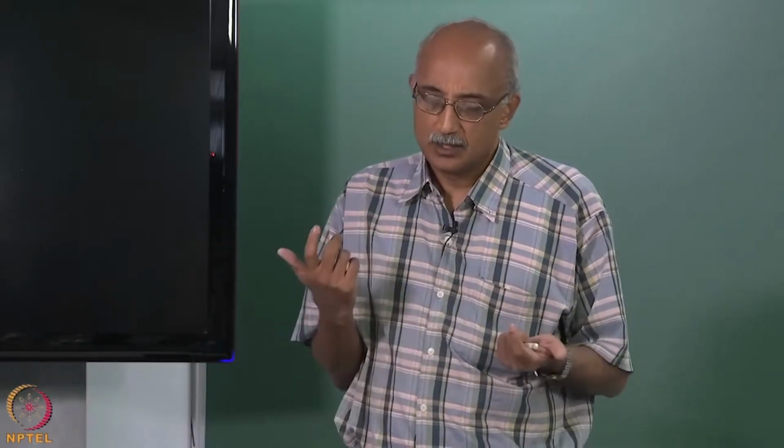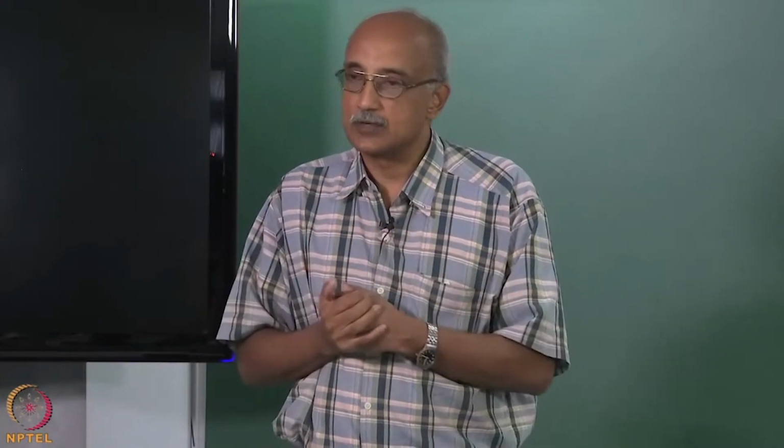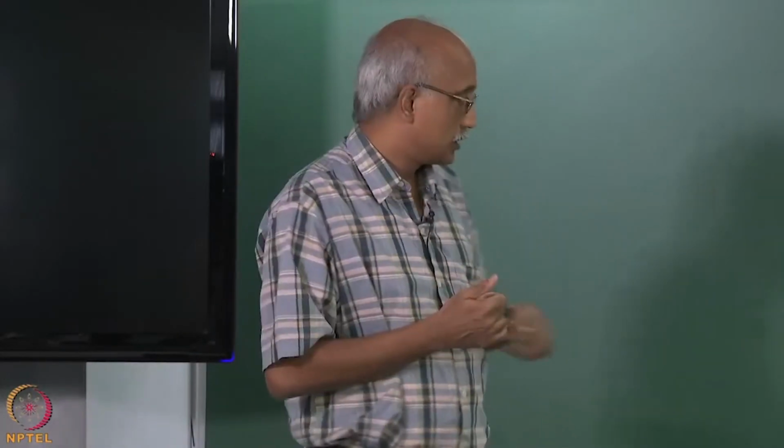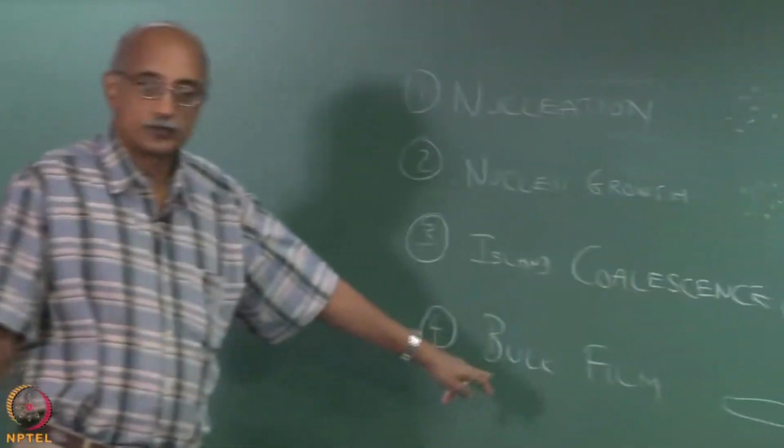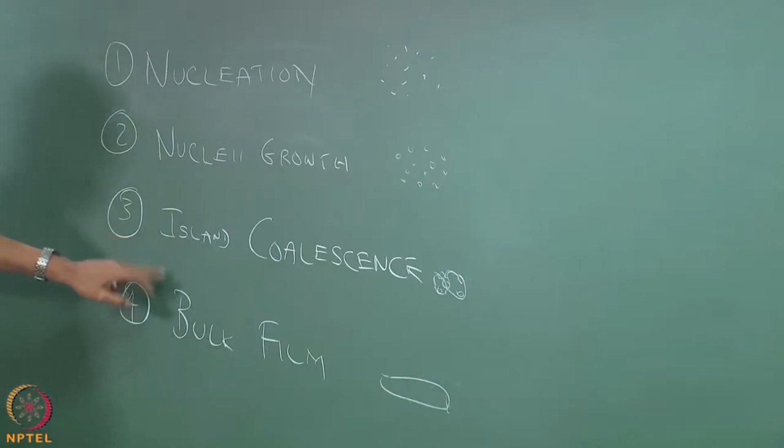But as it is, Teflon is an example of a very low surface energy surface which will not easily accommodate arriving vapor molecules. So, surface energy, wettability of the surface, how easy is it to form a continuous film on the surface, or is it going to keep breaking up? So, even after you get past stage 3 and you are trying to get to stage 4, is this transition again thermodynamically favored?